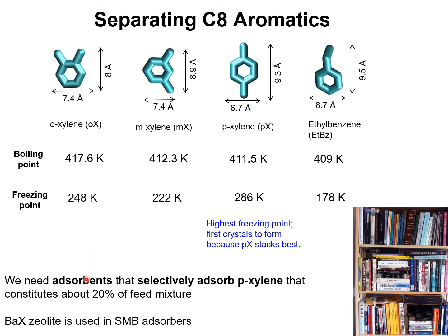Commercial units employ simulated moving bed adsorbers, and in most of the technologies that are offered currently, barium-X zeolite is used as adsorbent.